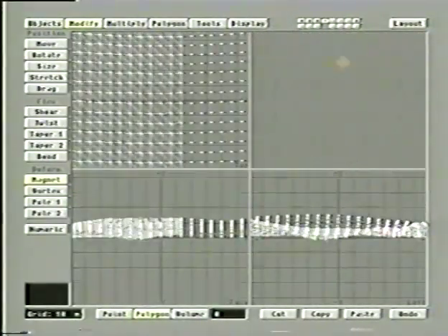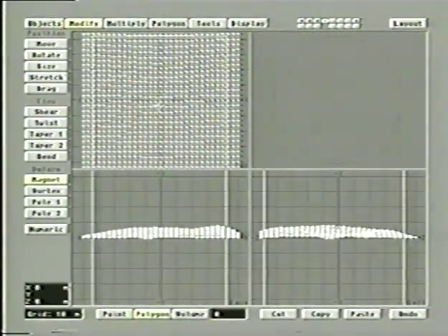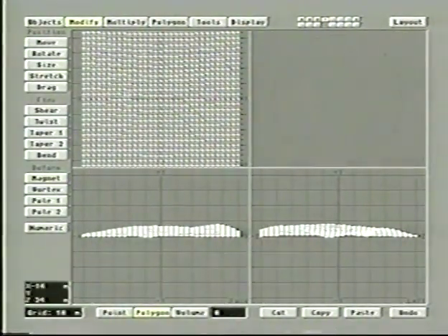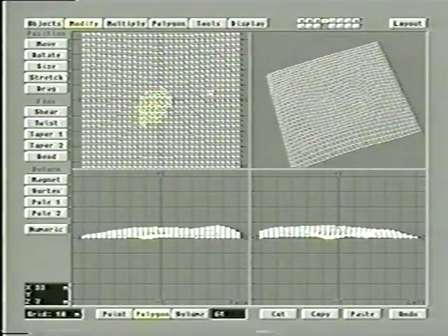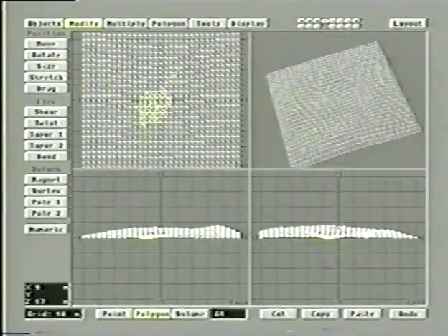Now what I'm going to do is back myself off a little bit, and I'm going to pick a bunch of the polygons in the middle. Because remember, this is where I'm going to have a house or something like that. So I pick a bunch of these polygons. And what I'm going to do is use a function called set value. Now what set value does is it forces whatever you have selected to move to a certain value. What we want to do here is take these polygons that we've selected and force them to be at 0 on the y-axis, up and down. Pretty straightforward. But this will make it so instead of trying to nudge it into place and, gee, I hope this is right, this will force it down at 0.